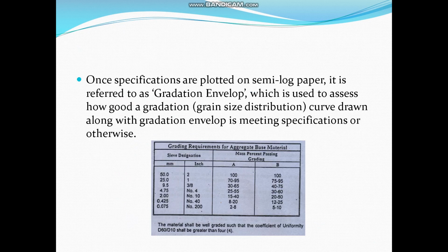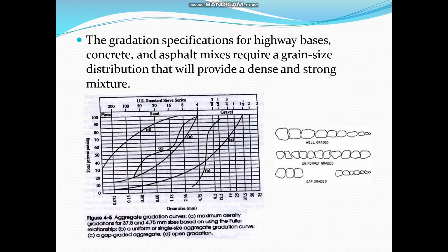And using the limiting values as shown in the table earlier, using a similar table and the limiting values, we can develop the gradation envelope, and I will show it to you in the demonstration after this. Using the material acquired on each sieve, we will be able to develop the gradation curve, and after the gradation curve we will see the type of curve that your material has.